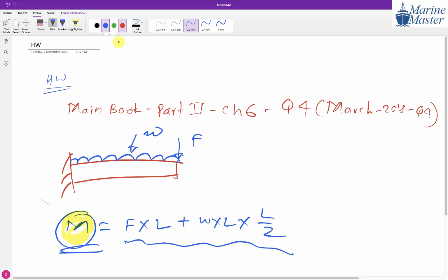See, guys, see this. Though I am showing some forces here, not all the forces are shown. Whenever there is a fixed end, a few things are going to develop at the fixed end. One is Rx, one is Ry, and one is a moment reaction. That is not our area of interest. So, guys, this is not simply a moment. This is a bending moment only, guys.